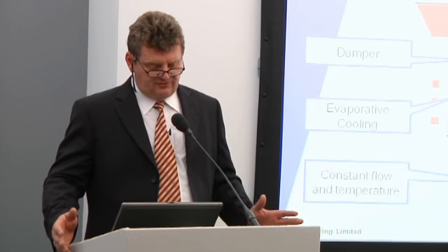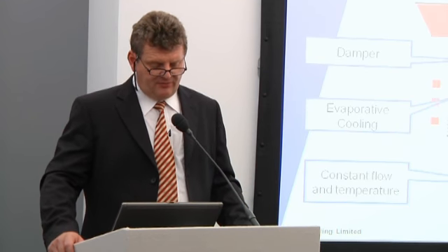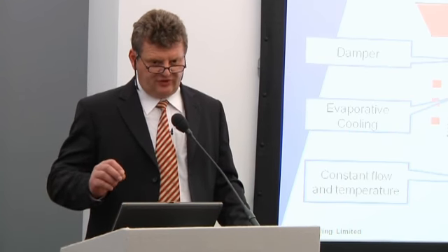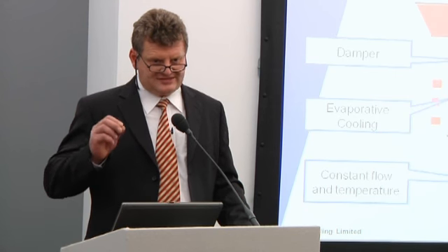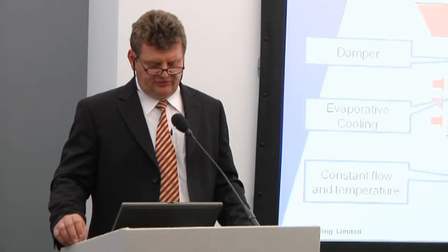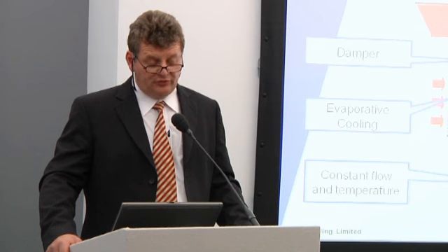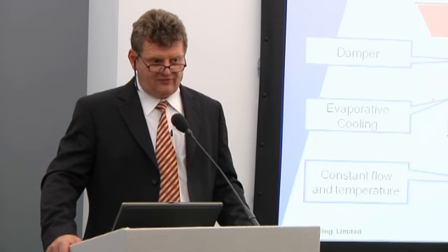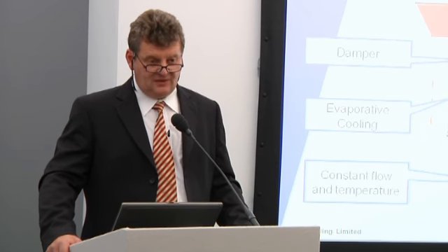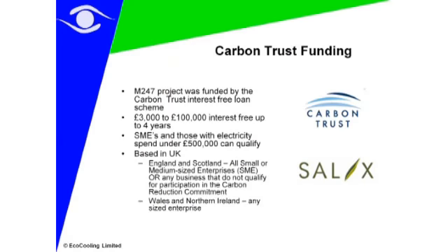Now this system, which is a patented system by Eco Cooling, provides us with this constant flow situation, which is sized to match the requirement of all those little servers, and giving us a constant temperature. We put no humidity control whatsoever into the system. The telecoms industry haven't used humidification for years now, so we're not really changing anything there.